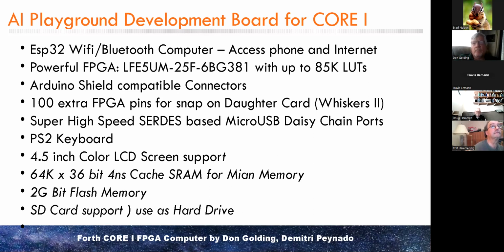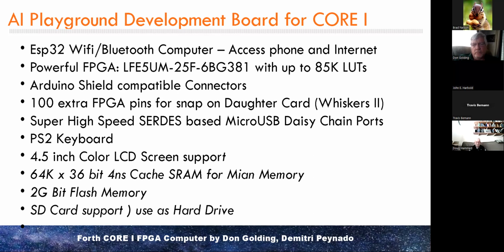Like, for instance, this isn't a shield, but SD cards natively have two modes, either 3.3 volt or 1.8 volt. To use an SDHC or SDXC card, that is, not the old original SD cards, with 5 volts, you need to use a board that converts the voltages for you.